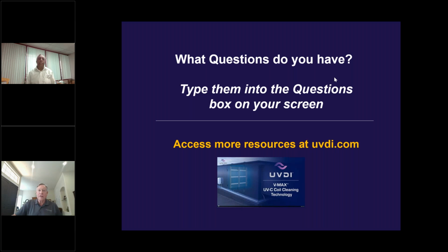Okay, thanks, Ashish. Here's a question with some newer technology. Are LED UV emitters available at the UVC wavelength? This is coming in from John. Yes, we've been watching LEDs for 10 years. It's only in the last 2-3 years where they've started getting down to the wavelengths which are germicidal. You could probably get an LED which is 265 nanometers. Even there are some companies saying 254 nanometers, which is the same spectral output of a low pressure mercury lamp.